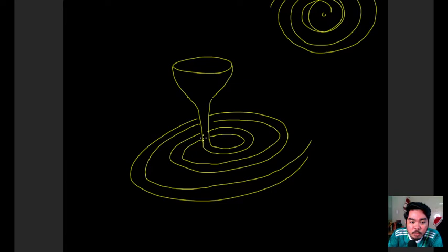When you pour this, there comes a point wherein it stops because it has already solidified. So you measure the total length, and that is the fluidity in inches. It is the total length it traveled before it solidified. So that's how your fluidity testers work, no?